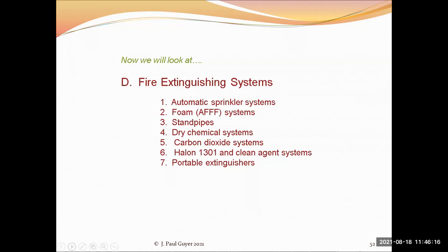And so there's a hazard to life. So carbon dioxide systems are typically used in unoccupied spaces like transformer vaults, things like that. The item 6 there, Halon 1301 and clean agent systems, these were developed a few decades ago, 2 or 3 decades ago, to deal with the